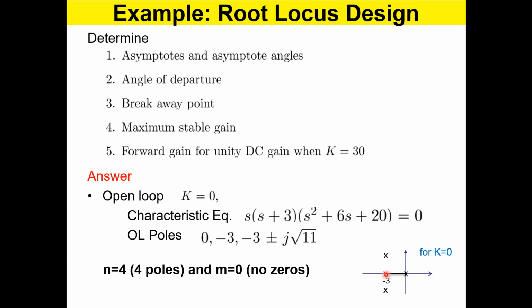And this pole will have to move this way, not any other way. Because we know this is root locus from here to here. So when you identify a part of the root locus, real axis or anywhere, you know that this is the path the poles take when you increase k from 0.